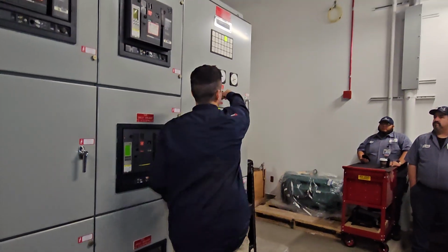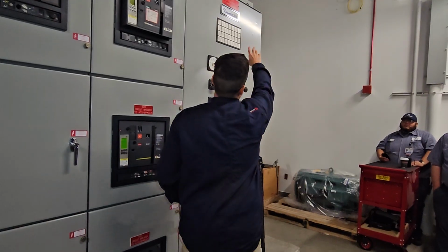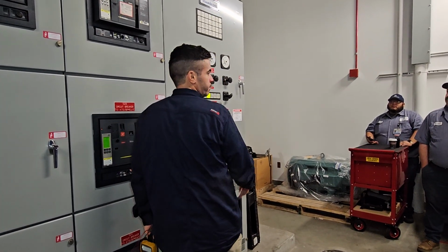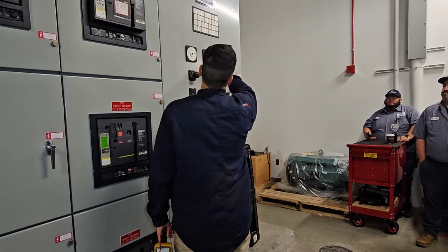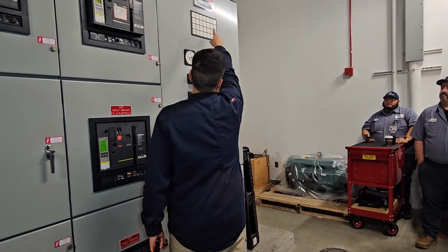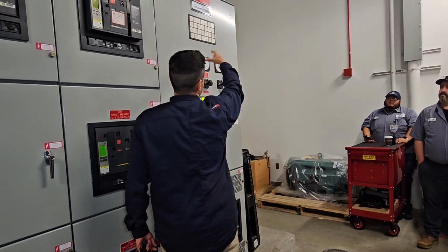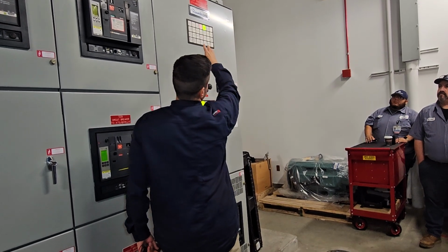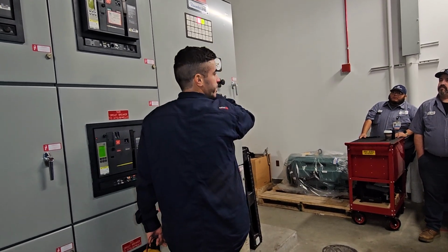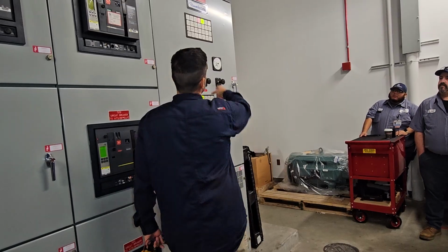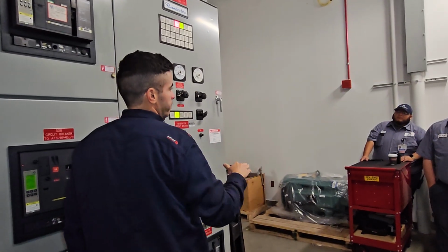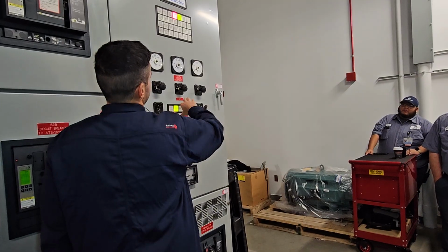I'm going to put this back in auto. Automatically the breaker got a trip signal. You guys heard the click, but the breaker is open, so it's not doing anything. The engine light starts flashing. That means it's in cooldown. If I turn it to off, it will remain in that condition, but it will say not available, which means that if it gets a start signal, it's not going to try to close. And if I turn it to stop reset, then it will shut off completely. Okay, so I'll keep it like that.